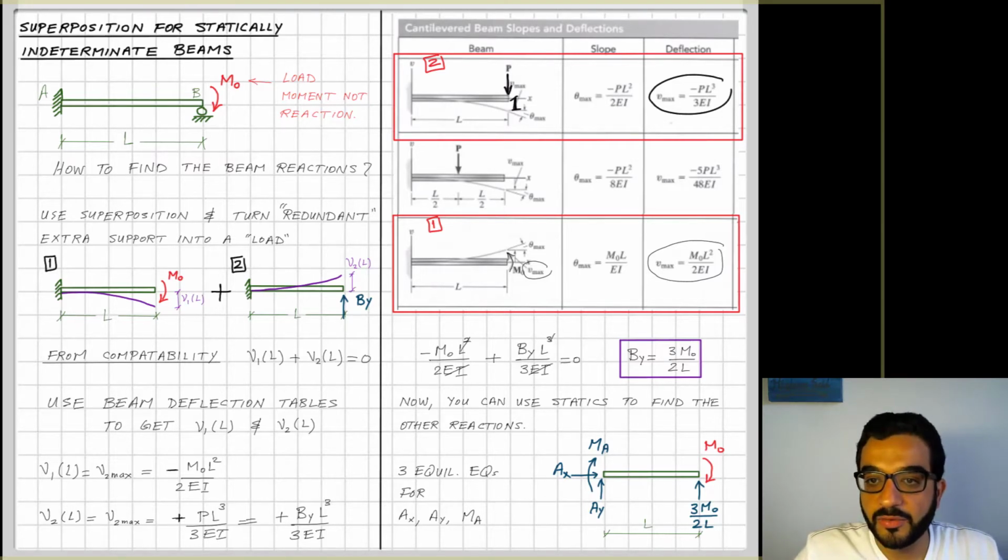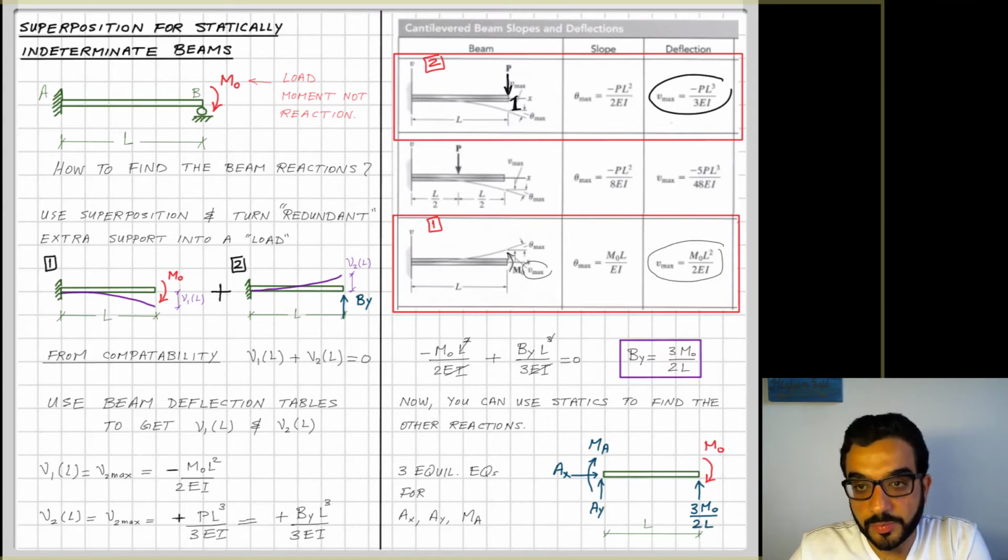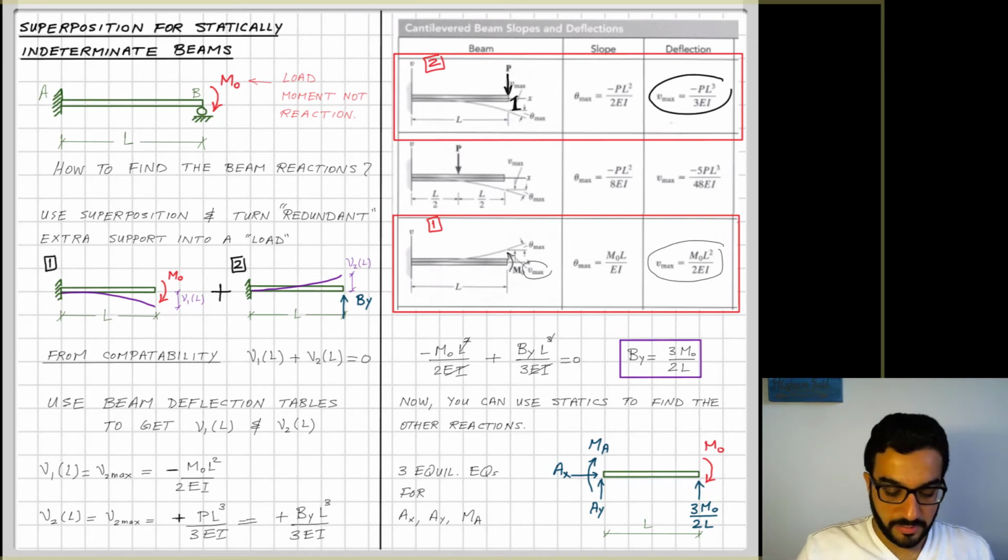But now we learn how to use the deformation and deflection information of the beam to be able to solve for more unknowns than I could have solved using equilibrium equations. One thing we have seen in this exercise is you have to pay attention to match the original problem load cases with the table load cases, and match them in terms of description of the load case and the direction of the loads applied.